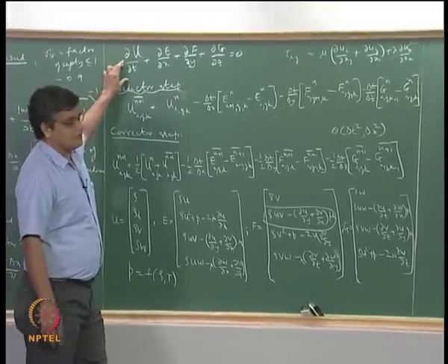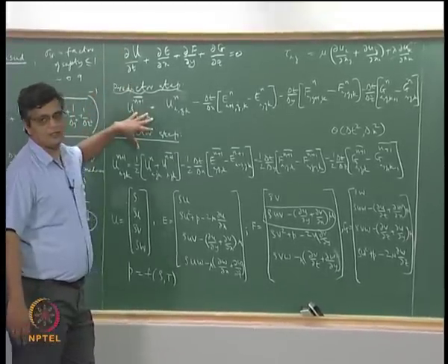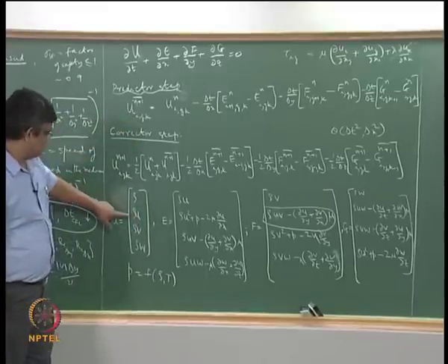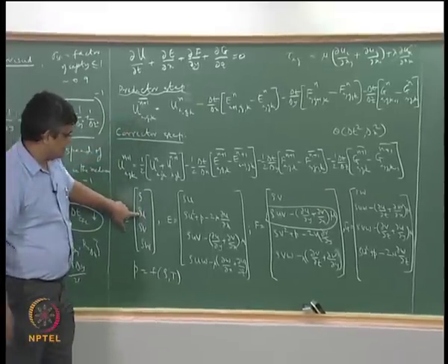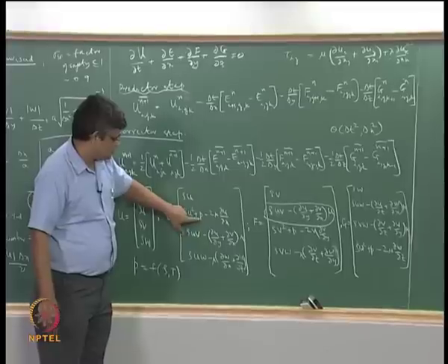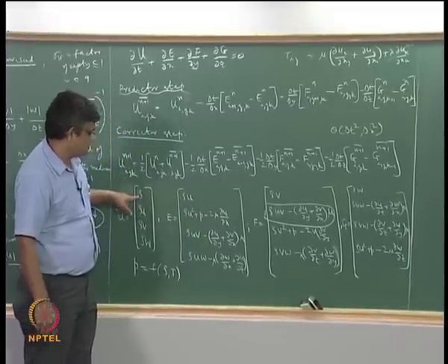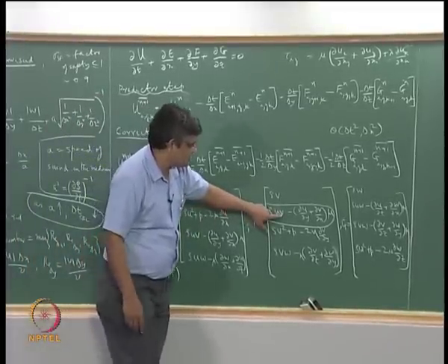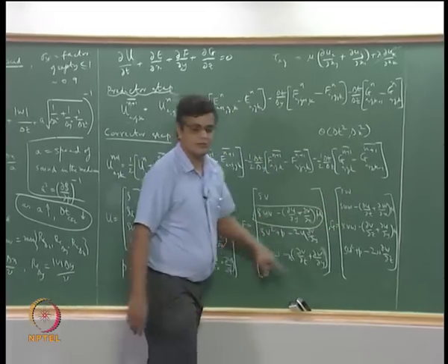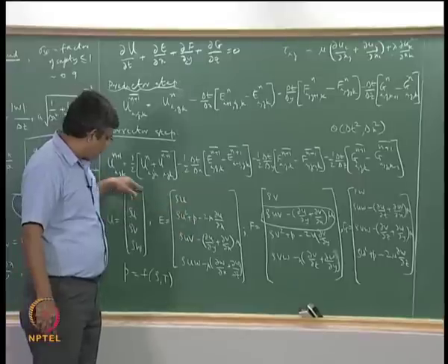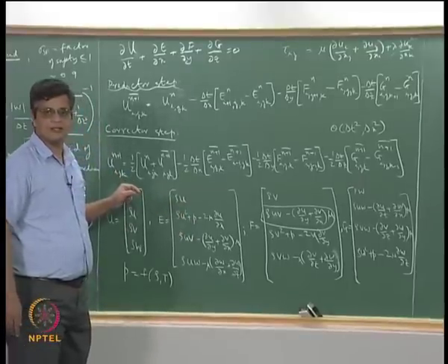And the problem that we have with the coupled equations, with the Navier-Stokes equations, is that if you want to evaluate, for example, the u velocity, not only do you have u, but you also have rho, which is indirectly p, which is indirectly coupled to u, and then you also have v here and then w here. So that means that in order to evaluate u, you need to know all the other variables that are incorporated in this.